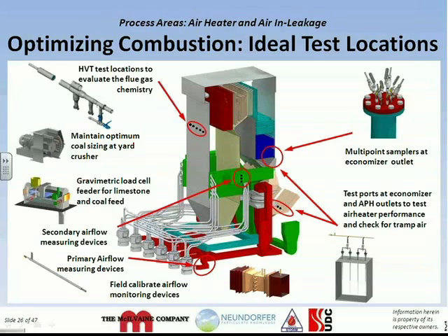as 5%. Often, we test as much as 15% excess oxygen. This is a lot of air in leakage, and it is very costly from a fan power standpoint alone. It's even worse when the heat losses are calculated. Dick, what about air in leakage at the air heater?